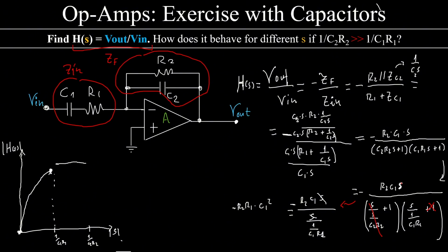And now I will just connect these approximately. This is an approximation. We want here to study the behavior of the circuit, so approximately, it's okay to do these things for now. This value will be how much? R2 C1 squared R1. This value will be constant, so this is constant up until a point. What is the point? Where the frequency becomes comparable to C2R2.